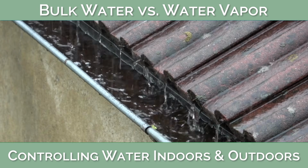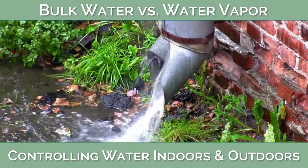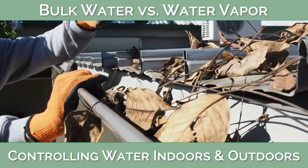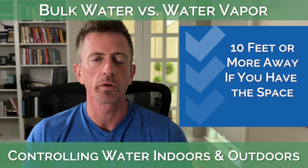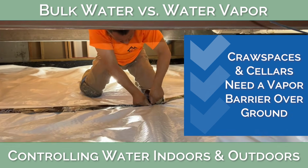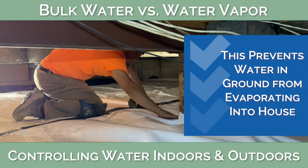Gutters and downspouts, along with extensions at the bottom of the downspouts, are used to direct rainwater away from the foundation of your home. So if you live in an area that rains often, it's really important that they be free of debris and able to move rainwater away easily, at least 5 feet away from your house, and 10 feet or more is preferred. If you have a crawl space or a cellar, it's very important to install a vapor barrier over the entire dirt or gravel floor to prevent water from evaporating up into the house.